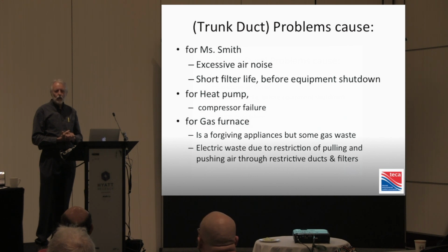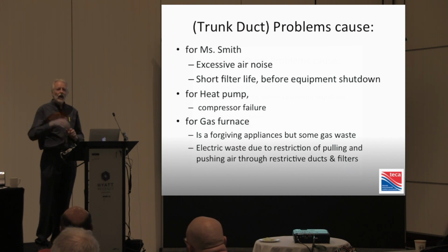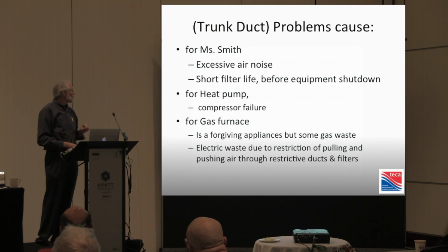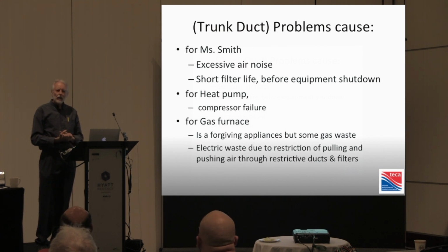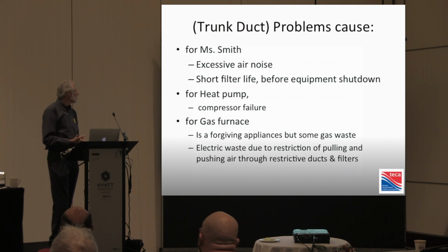And it's a lot of work with a good tech to clean that system out so you don't smoke the next compressor as subsequent failures. So if you're using heat pumps, be sure you've got a good ductwork person on the job, and I'll show you what happens when you don't.